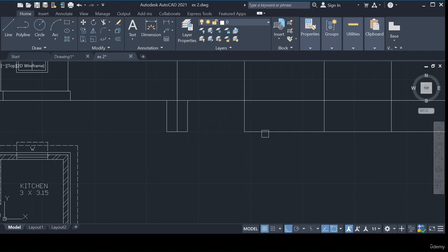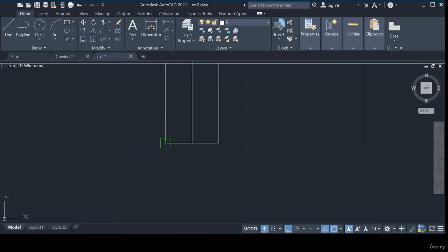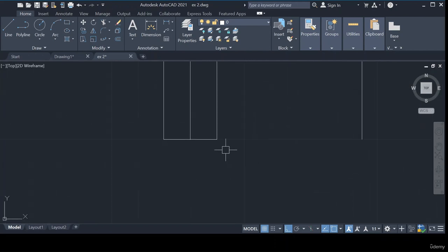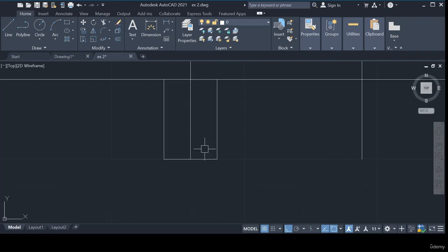I just trim the extra part. Let's trim this one. We don't want all those things. So depth of the foundation is 1.5 and width of the foundation is 1 meter. Correct. So once the excavation is done, next step is we need to provide the PCC. We go to the offset. What is the PCC thickness? 0.1. It is already mentioned here, 0.1.